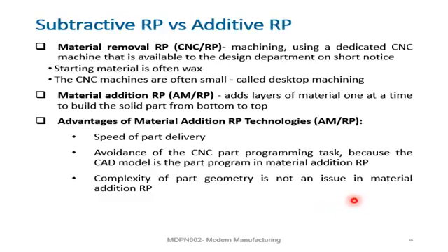But now, to make a rapid prototyping model, the first model, usually it can be built from soft material like wax. Before you go into building the real one using tool steel, for instance, you create a rapid prototype very quickly by this, and you can examine it, and if you feel okay, you can go to the real production by the CNC approach, for instance.